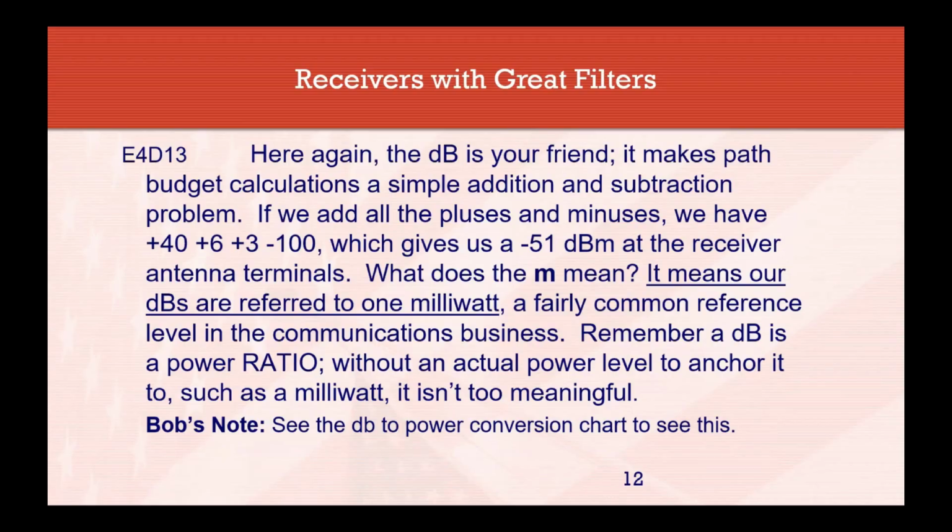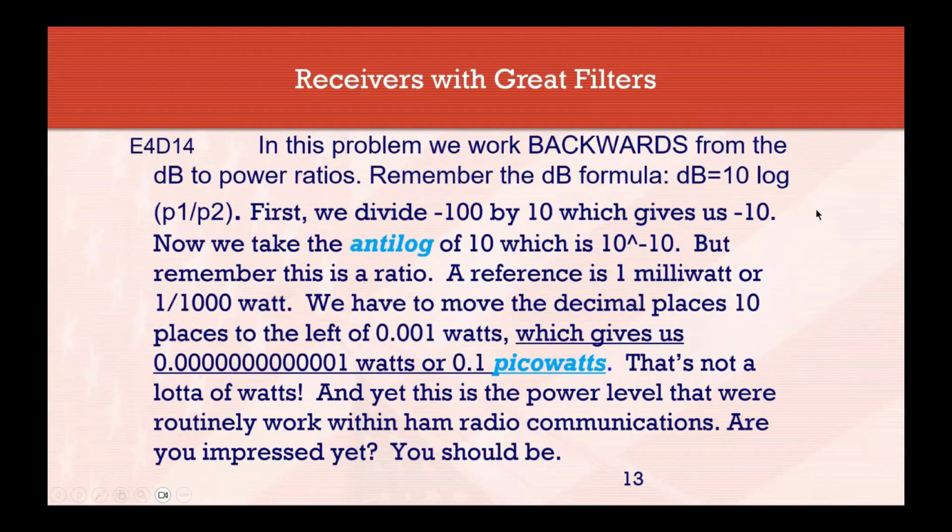How much greater is one voltage than another? How much greater is the power of one signal than the power of a second signal? For our power calculations, dBm means we're referencing the 1 milliwatt. So how much stronger or how much weaker is this signal than 1 milliwatt? One of the things that I emailed to you during the week has a conversion chart where you can look these things up and get a good idea of what those things will do as they go up and down that chart.